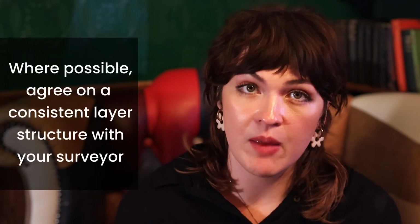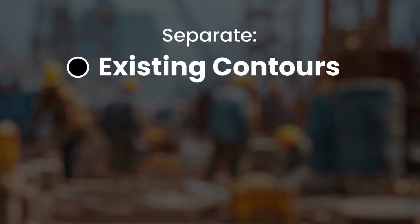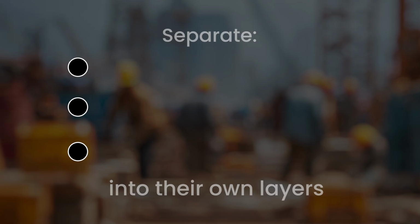It's worth noting that if you do regularly receive drawings from the same surveyor, it can really be worth agreeing on a consistent layer structure. Separating existing contours, proposed contours, and break lines into their own layers can really make the import process much easier. But of course, you won't always have control over how a drawing is presented, so it is really useful to know how to work with whatever you're given.